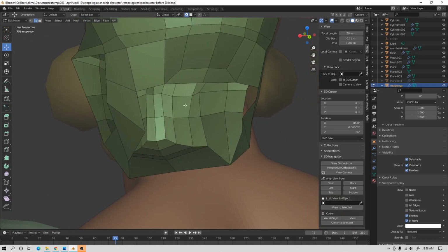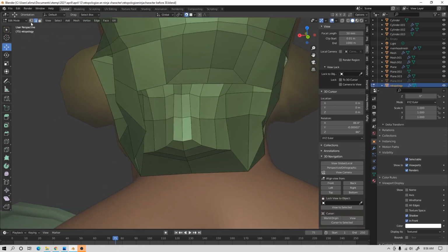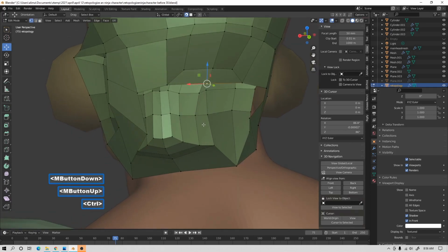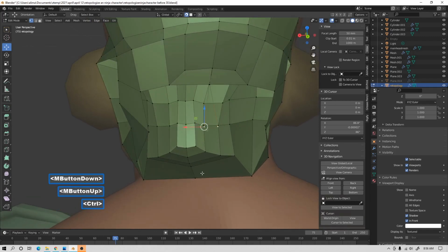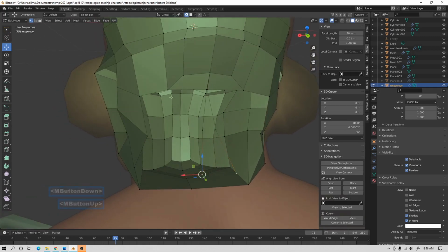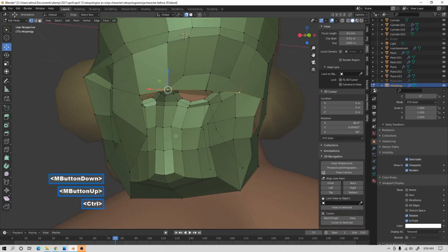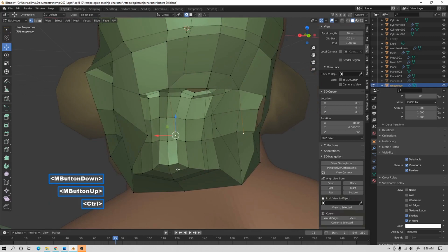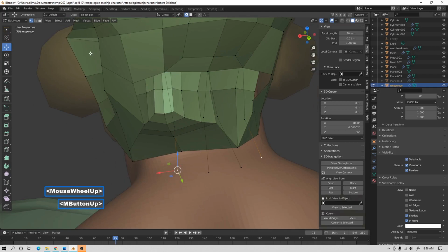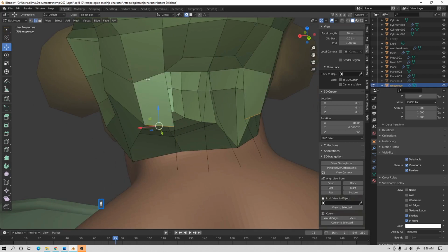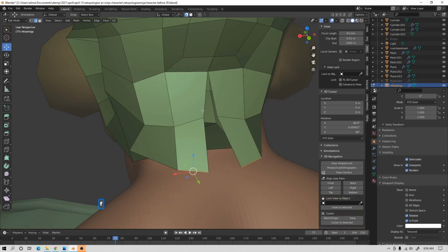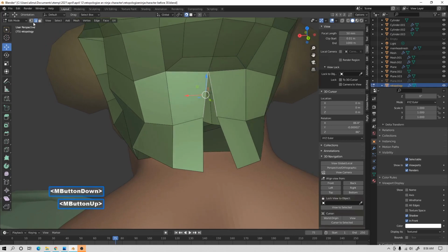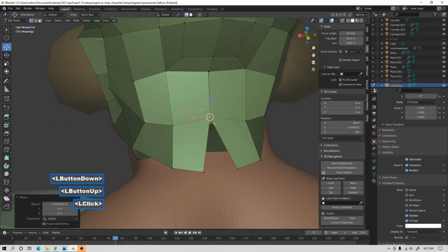Anyway, so we have this geometry here. What we can do is go to vertex select. We'll select here, hold Control. When I'm doing this, you see how I'm thinking: okay, we can have 4 faces here. So I'll select here. Remember, we can't see anything because we have In Front set for the display. However, once we have this geometry here, Blender helps us out because we can press F, F, F, F. I find the way that I split this here works better for me, making the geometry and then pushing it towards the center line.